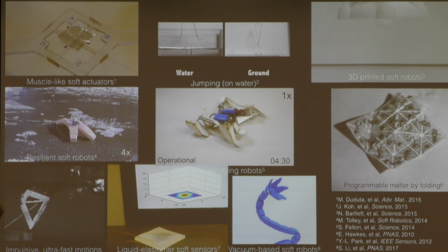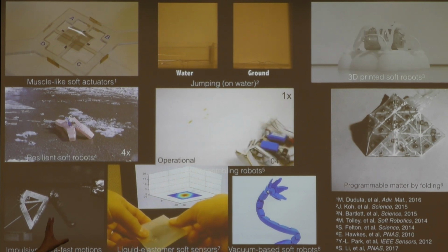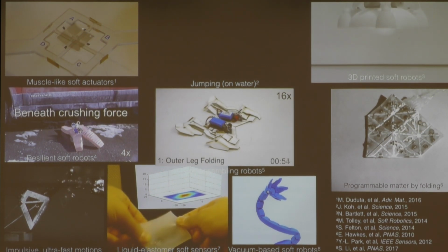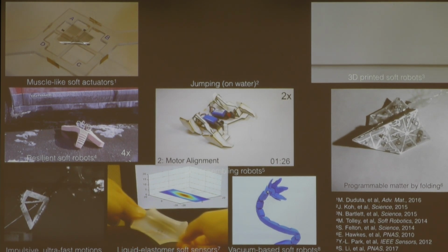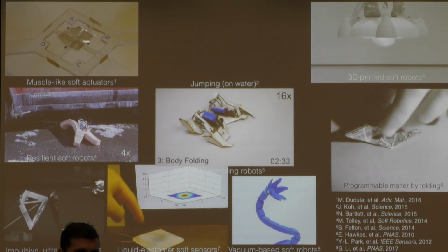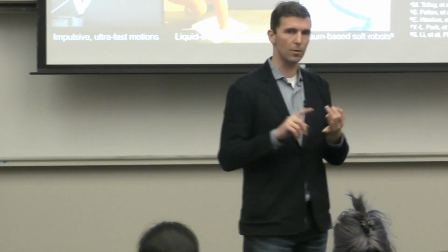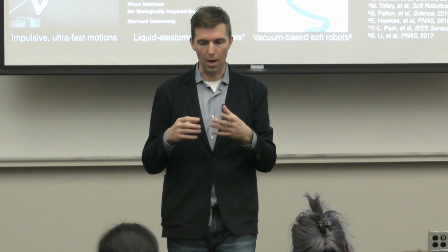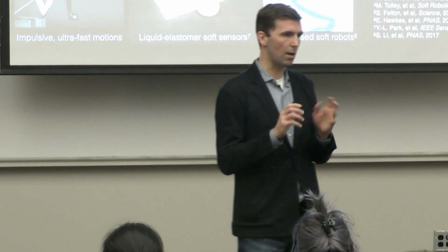And so we've got a lot of work recently, and there's a new paper which I didn't have time to include here that just came out describing multi-layer dielectric elastomer actuators that have many thousands of layers that are in exactly muscle-like form factors. So what are the downsides of dielectric elastomers historically? They require tremendously high fields, they require pre-stretch, which typically leads to rigid frames, and they require strain-compatible electrodes.